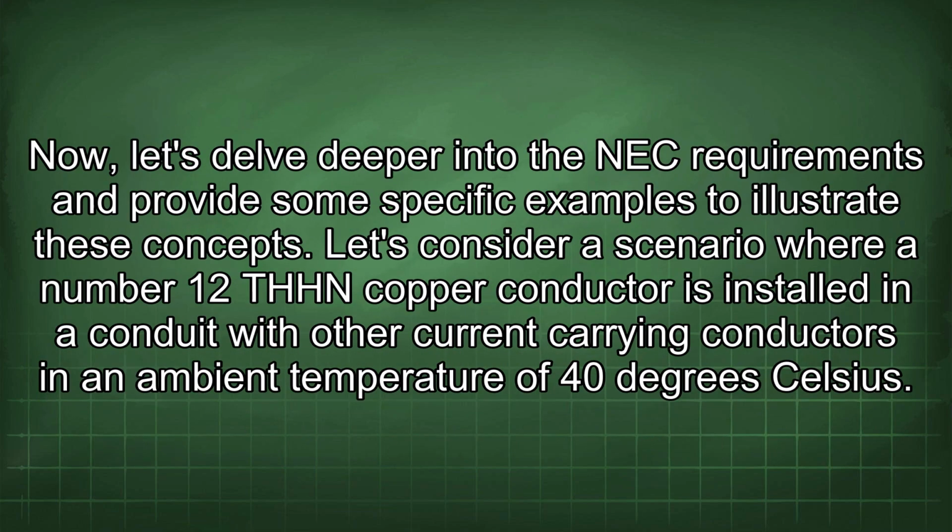Now let's delve deeper into the NEC requirements and provide some specific examples to illustrate these concepts. Let's consider a scenario where a number 12 THHN copper conductor is installed in a conduit with other current-carrying conductors and an ambient temperature of 40 degrees Celsius.